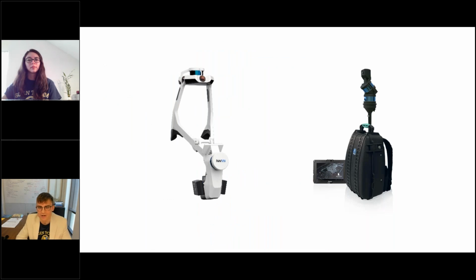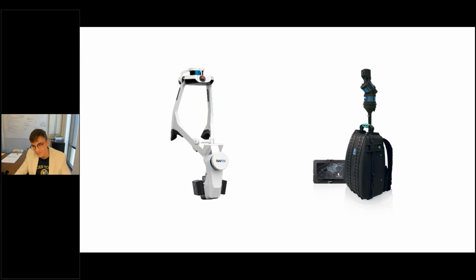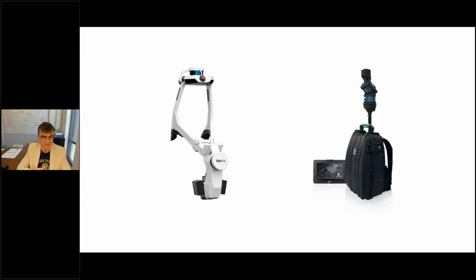Mobile scanners are faster than terrestrial tripod-mounted scanners, but they're less accurate. They achieve better coverage because effectively you're scanning from millions of perspectives along a scan path. If for logistical reasons you're scanning from an unstable platform like a man lift, a mobile scanner would be better here than a tripod scanner because it's not affected by that movement.